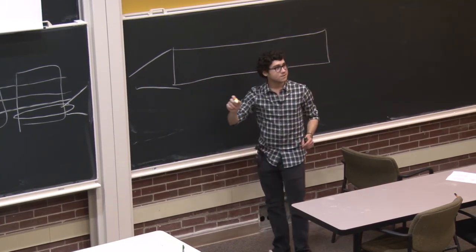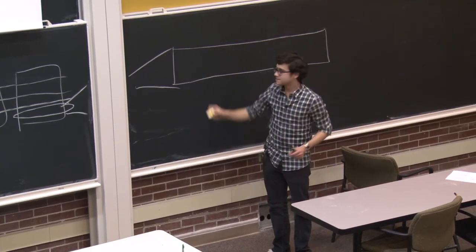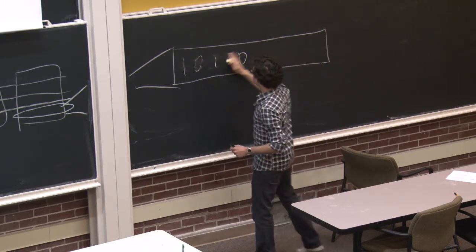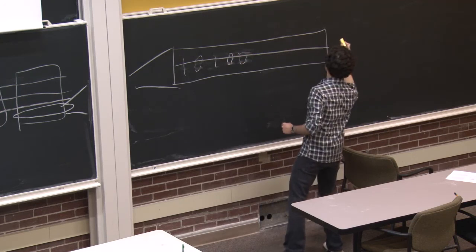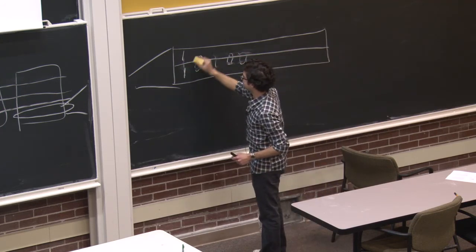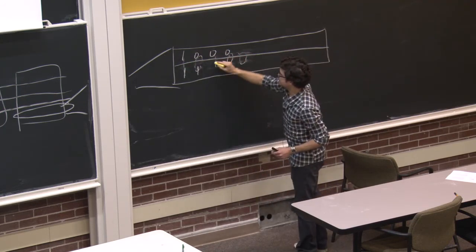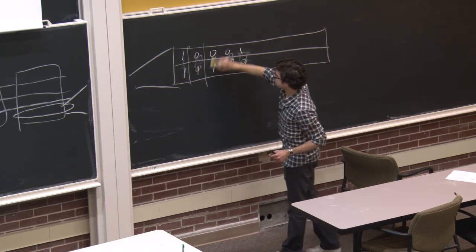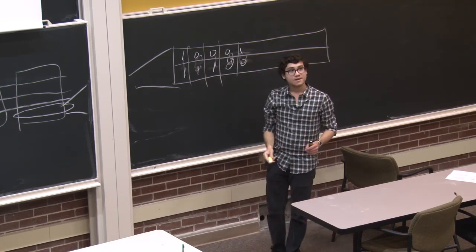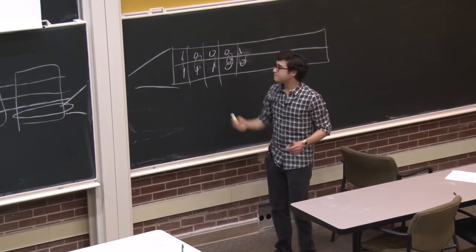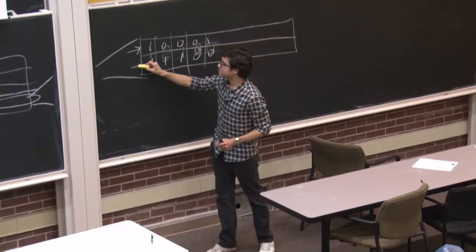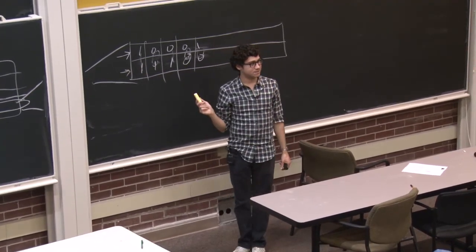In multiple bit technologies, instead of just having 1, 0, 1, you actually have this sort of organization where you have multiple bits being used in each cell. These are cells. And the operating system can map a page to this lane of cells and another page to this lane of cells.